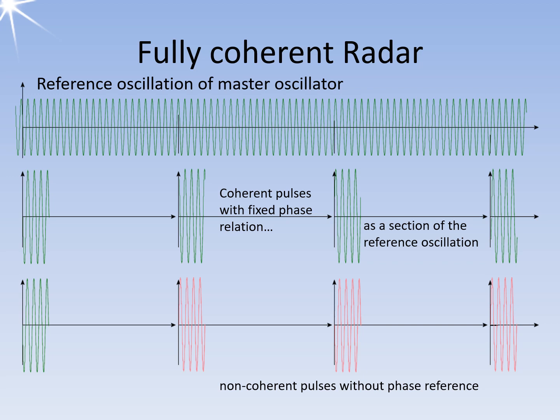However, there is a circuit trick in which the transmit signal synchronizes a coherent oscillator, which then continues to oscillate with the phase of the transmitter during the reception time, thus storing the phase of the transmit signal. These radar sets are then called pseudo-coherent or coherent on the receive path. In this way, a radar with a magnetron transmitter can also detect moving targets, although not as effectively as a fully coherent radar.